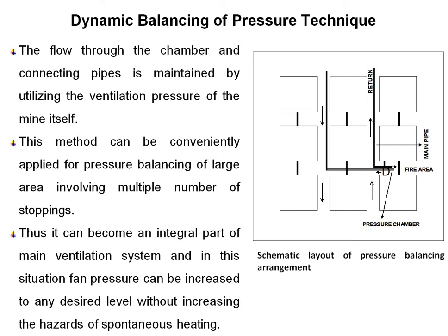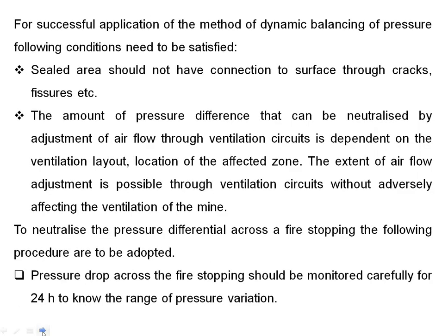So the method can be conveniently applied for pressure balancing of a large area involving multiple stoppings. Thus it can become an integral part of the mine ventilation system, and in this situation fan pressure can be increased to any desired level without increasing the hazards of spontaneous heating, so that pressure balancing can be possible, and an adequate quantity of air can be supplied to the working faces. So this is a big science, but I will discuss it further.